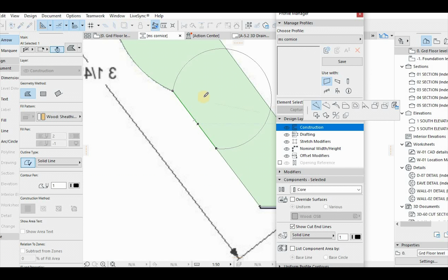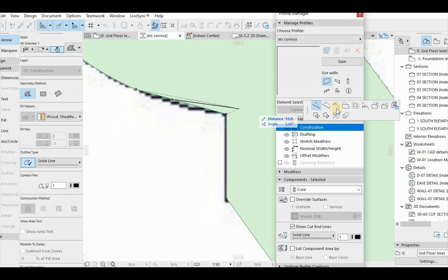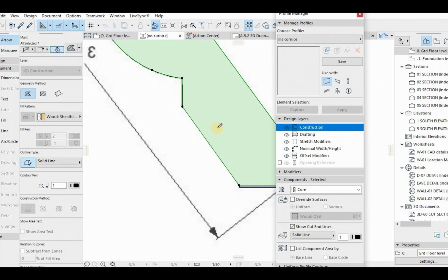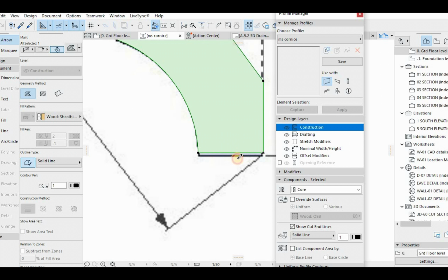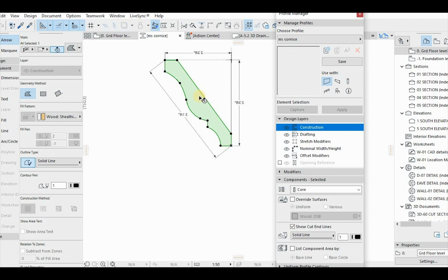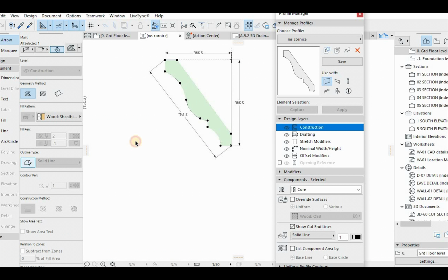If you're drawing a cornice like this, you just outline the cornice with the fill, and then assign the building material to the fill. If the cornice is pine or whatever wood, you assign that material. If you're drawing balustrades, you assign the balustrade material. If you're making a cavity wall, you assign different kinds of fills. You can have different kinds of fills in the complex profile. The point is to achieve whatever object you want.